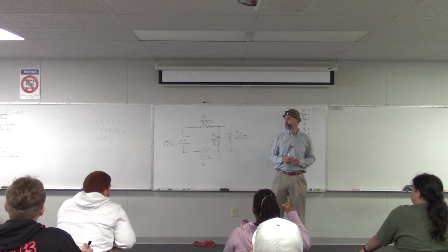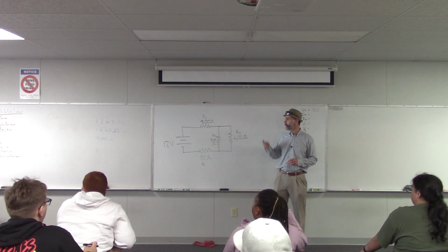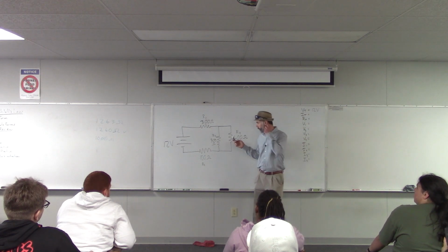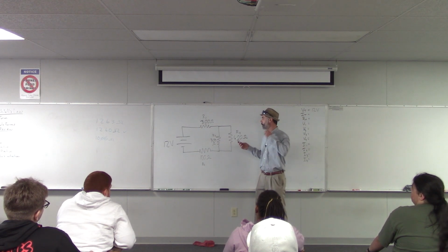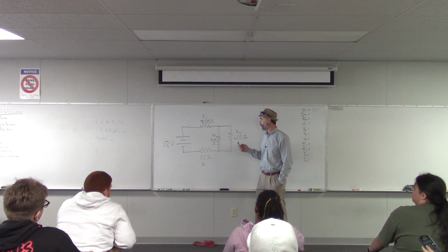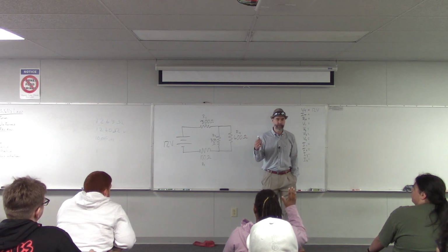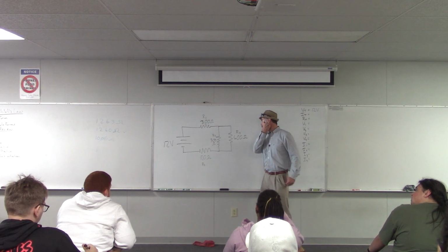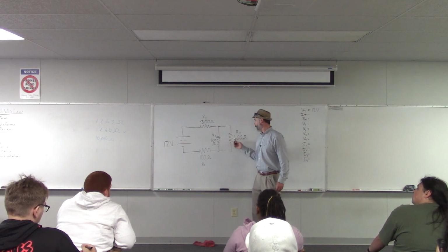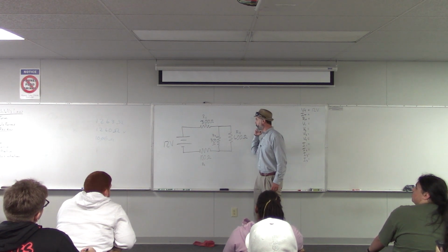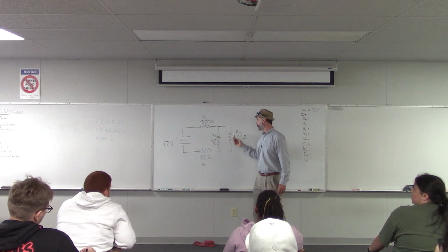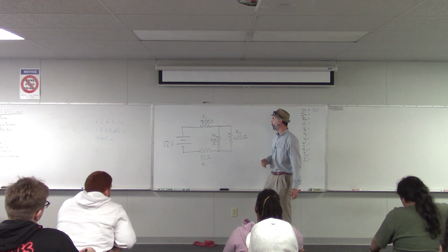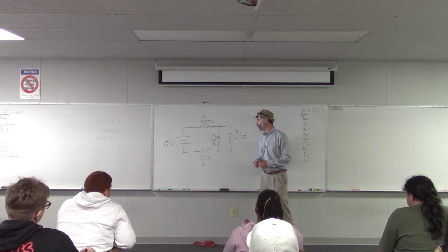Number of resistors and then divide that by the number of resistors. Well, yeah. So we can look for resistors that are in series or parallel and then find their equivalent resistance. You can simplify R3 and R4 and find the equivalent. Perfect, yeah. So R3 and R4 are in parallel because their tops are connected to each other and the bottom resistors are connected to each other as well. So we can simplify those.